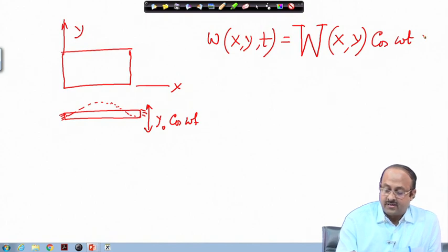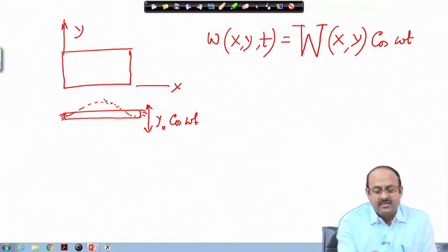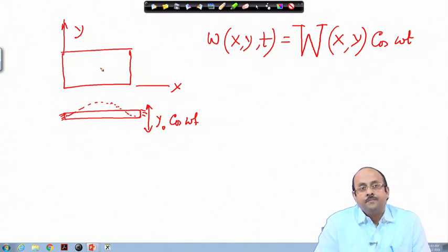Then of course, the acceleration. So, we will consider this part because this has a number of different modes. It is only the first few modes which are quite prominent, because the other higher order modes, which will have higher natural frequencies, will not contribute too much to the vibration. So, it is only the first few modes which will contribute.